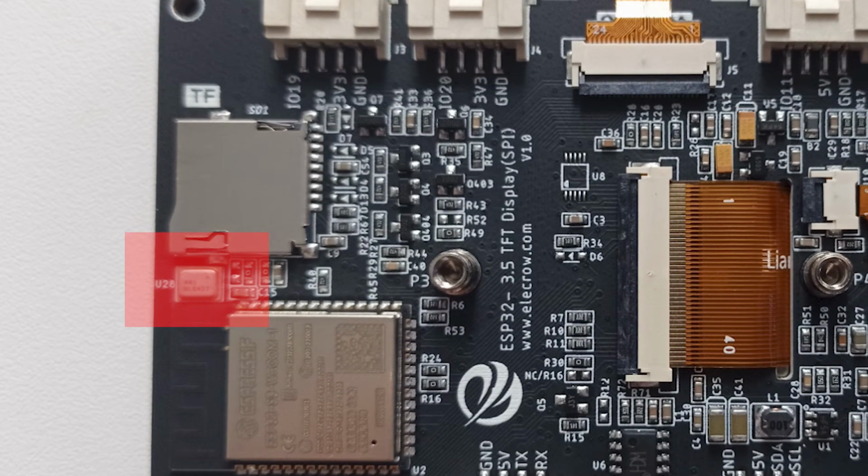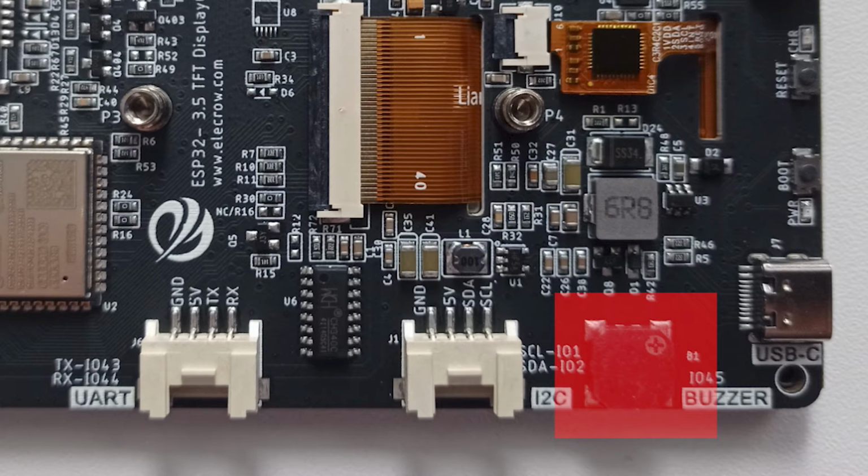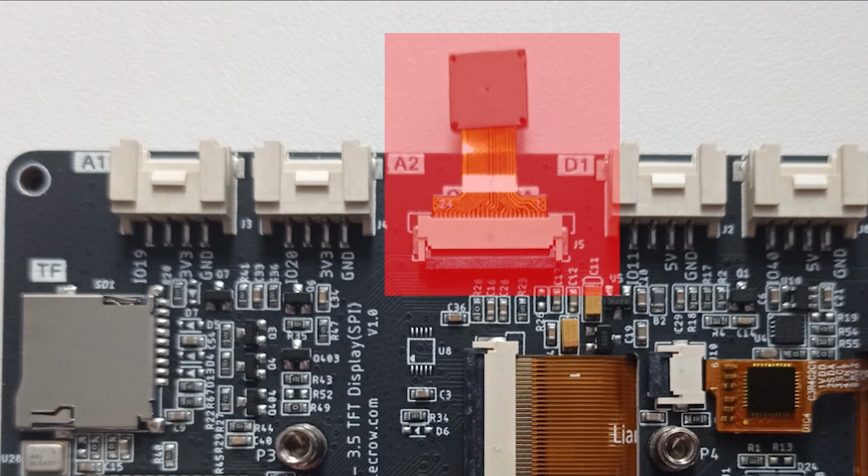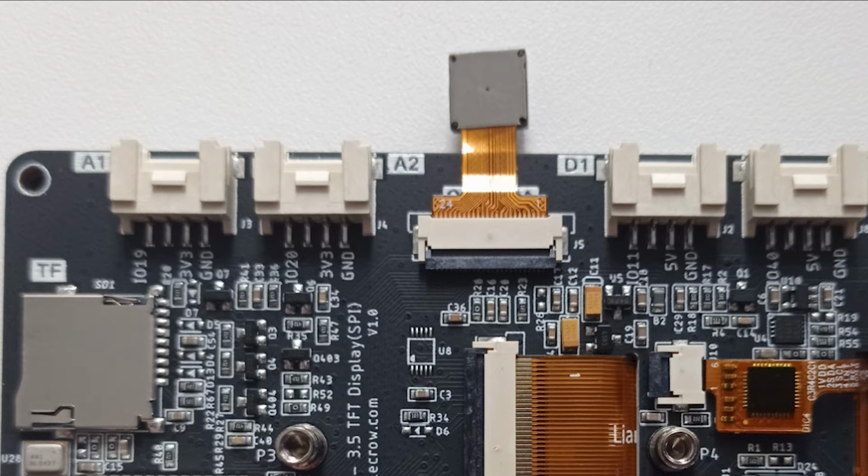Additionally, on this unit, Elecrow have attached a MEMS microphone and a small buzzer, and I'm not quite sure whether that's just a simple buzzer or an actual speaker yet, but we'll find out later on. Now, power to the board is through a USB Type-C connector, and just above that we've got the reset and boot pins for programming the ESP32. The camera itself is attached via a removable ribbon cable, so I guess we could either remove the camera completely if we just wanted the LCD panel, or replace it with a slightly longer ribbon cable if we need to mount the camera in a different position.